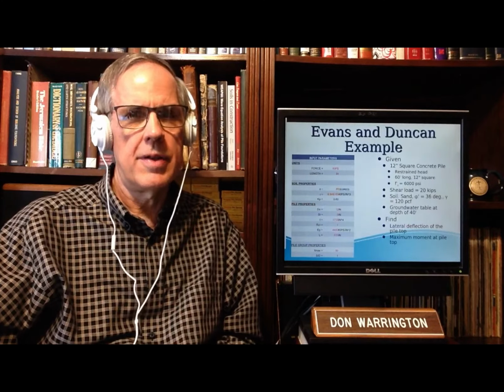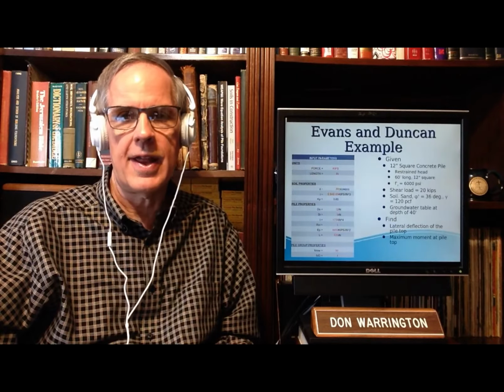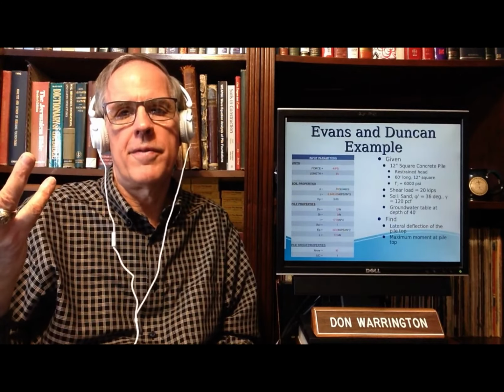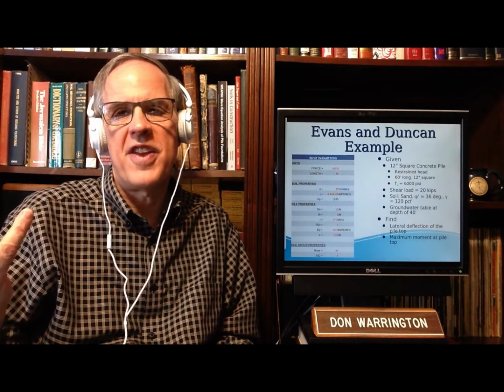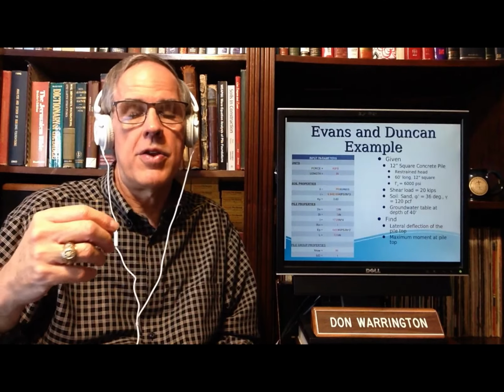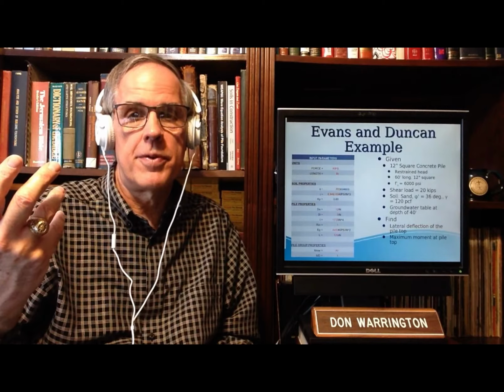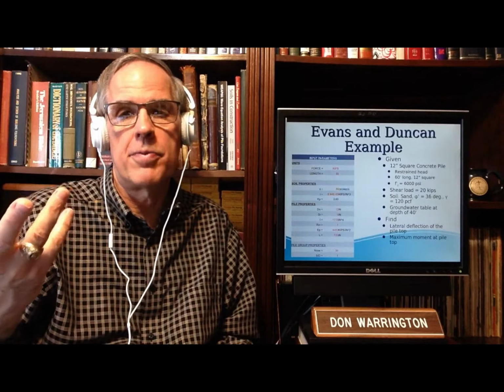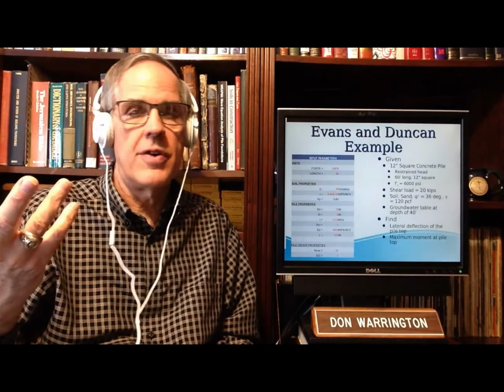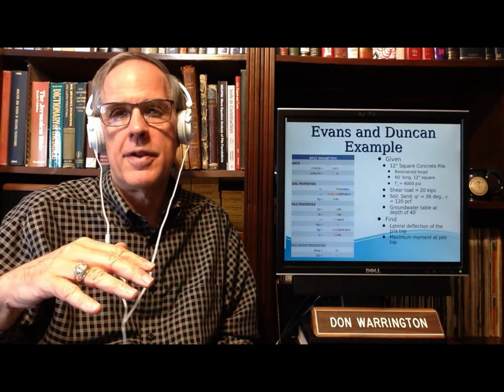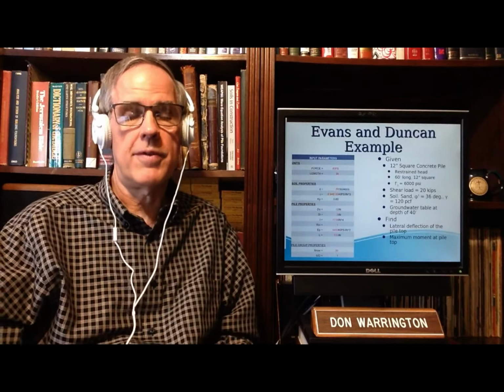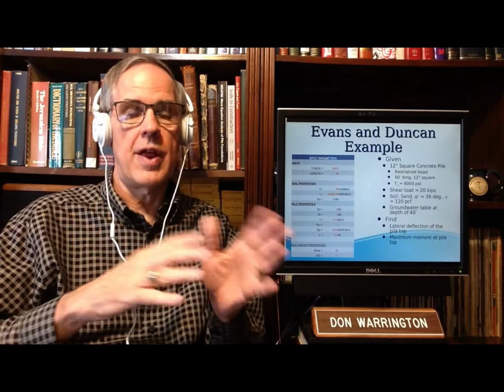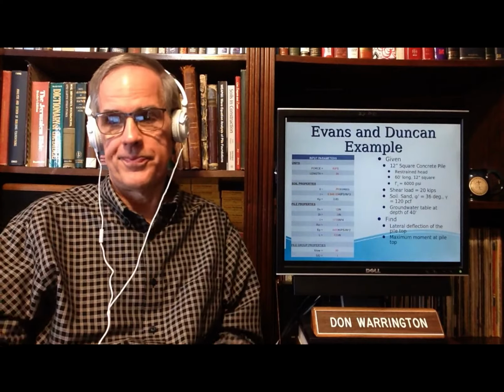So that's a little bit of a trap. You've got to be careful with the way you put your units in with this spreadsheet. It doesn't tell you, oh, I could put my length in feet, which would make sense, my unit weight in pounds per cubic foot or kips per cubic foot, and then turn around and say the pile dimensions are in inches. It won't let you do that. If you use inches for one unit, you have to make sure that everything is right.